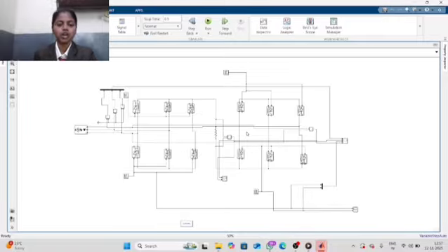During the positive half cycle of the required output waveform, the positive converter group conducts from the 3 available input phases. The control circuit always selects the phase that has the highest instantaneous positive voltage. During the negative half cycle, the negative converter group conducts and the same process happens, but the control circuit now chooses the phase with the most negative instantaneous voltage.